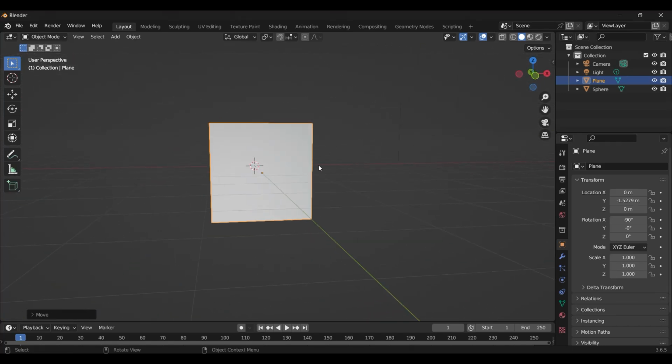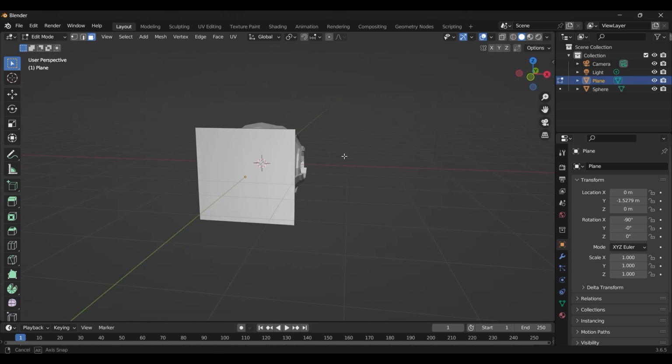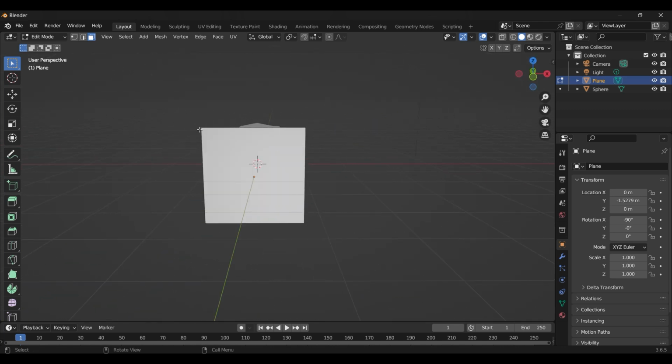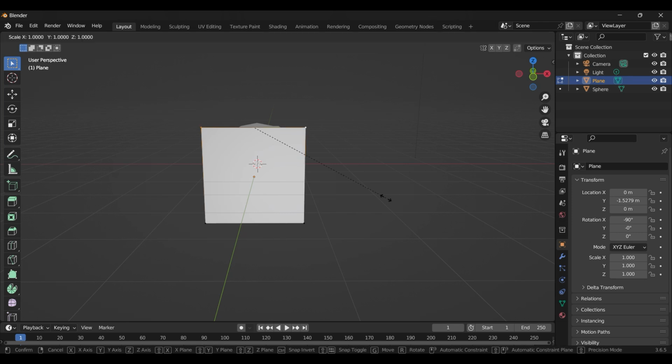And then whenever you press 1, as we can see, our plane is on the side of our core. So what we can do with this is press Tab. After pressing Tab, we enter edit mode. Then we have to select the first one, the vertices mode, and then select the first two vertices and press S to scale this like that.